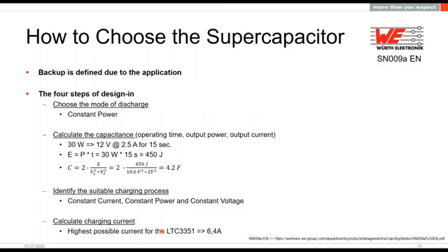So now let's start talking about the passive components, how you can choose the supercapacitors for such kind of application. A good tool for that is our support note SN009. Here we describe a few steps of what is important to consider. And first, we have to define the mode of discharge. With our IC here, it's constant power.